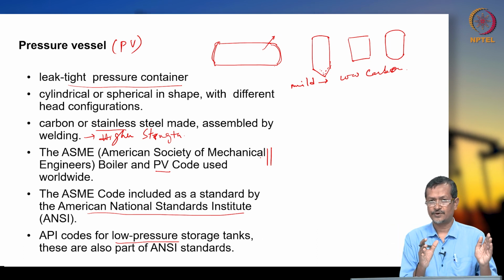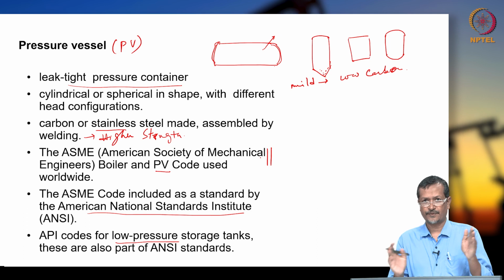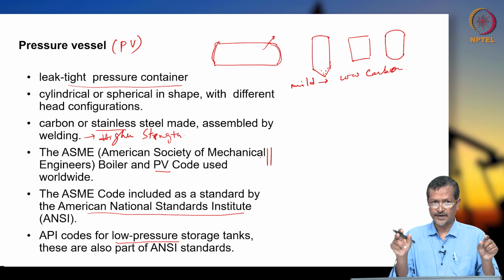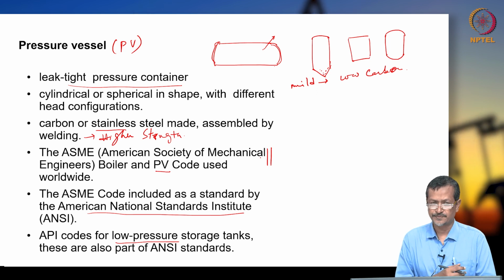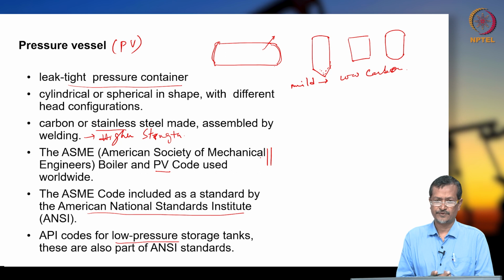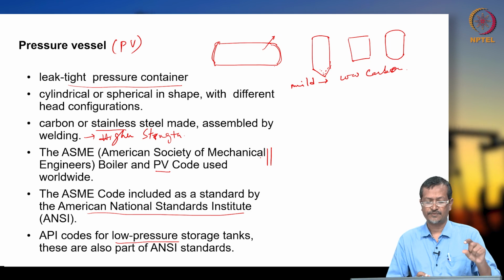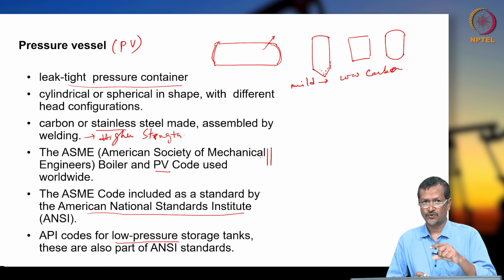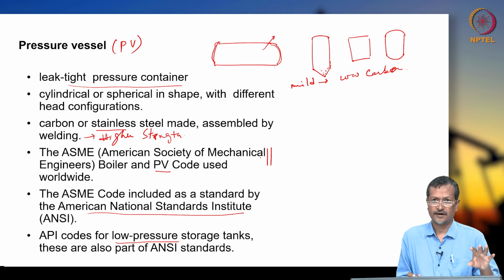So first you have to know your pressure requirement. For example, you want to work for 1000 to 1500 psi pressure. So within that limit you have to design the pressure vessel. Let's say you are designing for 5000 psi because you are thinking my pressure will be 500, and if I design for 5000 then everything will be safe. But it will increase cost because your material thickness will change, your design criteria will change. So you don't want to increase your cost, and again you don't want to create an accidental burst or any harmful thing.